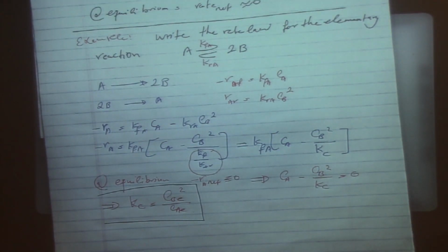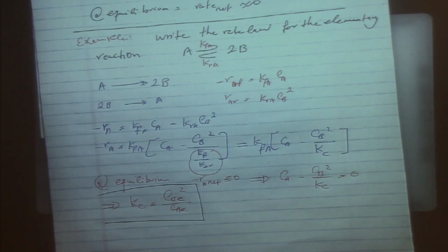Okay, so I'm going to start chapter 4, which has to do with stoichiometry. Recall the five Legos that we defined for this course. We started at the bottom with the mole balance, which was the design equation, then the rate law is the second Lego from the bottom, and the third one is the stoichiometry.